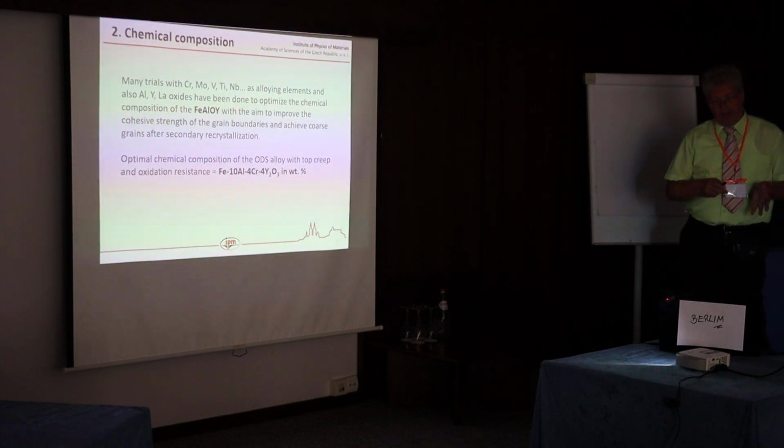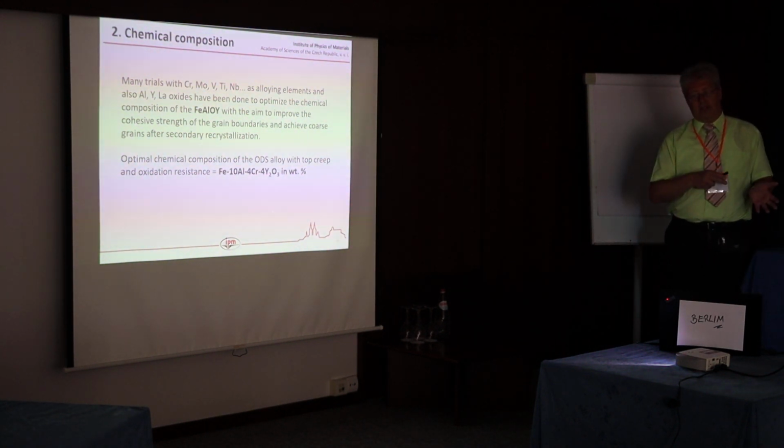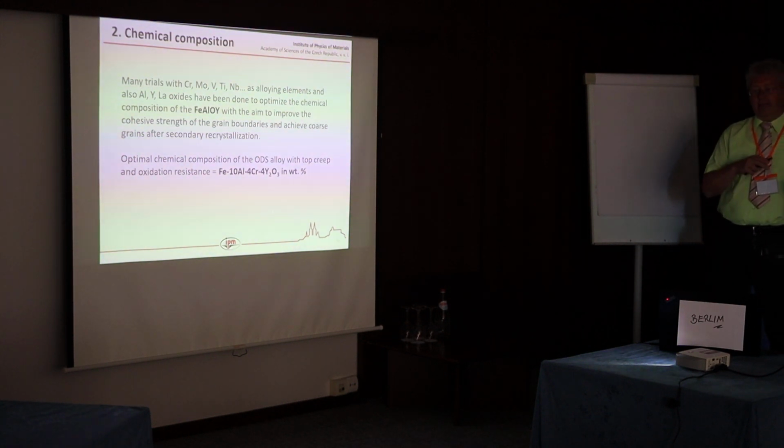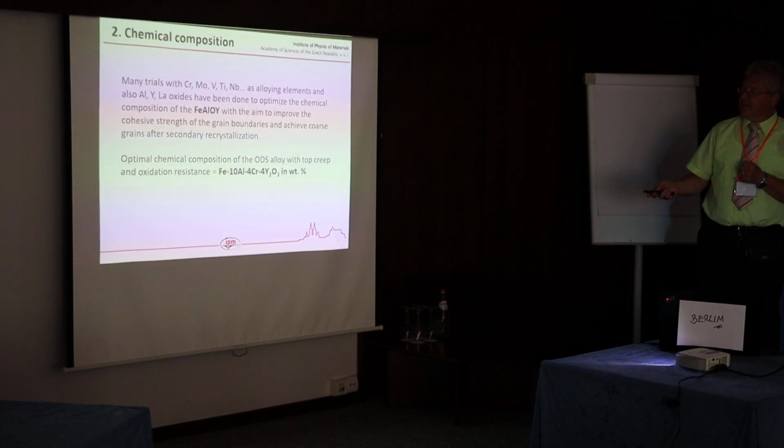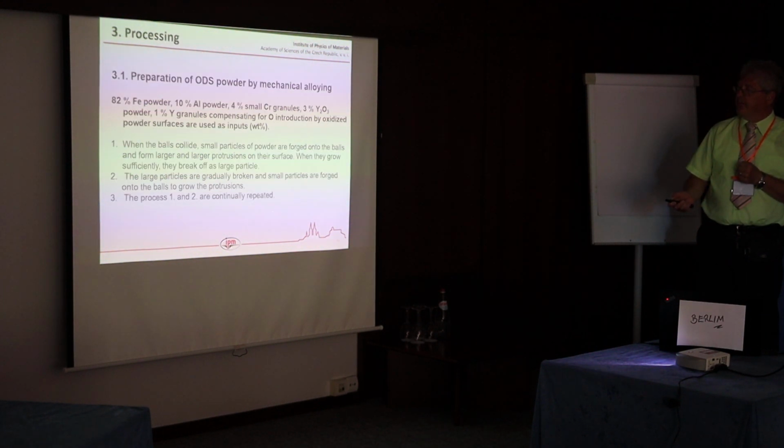And what we found at temperatures of about 1100 to 1300 degrees, the best composition is this one: 10% of aluminum, 4% of chromium, and 4% of yttrium oxide.